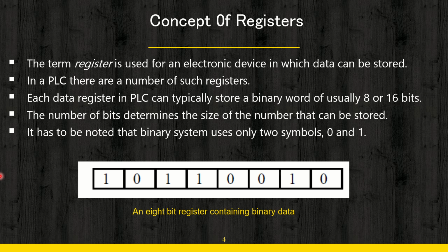There are some registers in the PLC for which you can manipulate each and every bit of data, and in some cases you cannot play with each and every bit. You have to change the entire 8 bits or entire 16 bits of data as per the specification of the register.